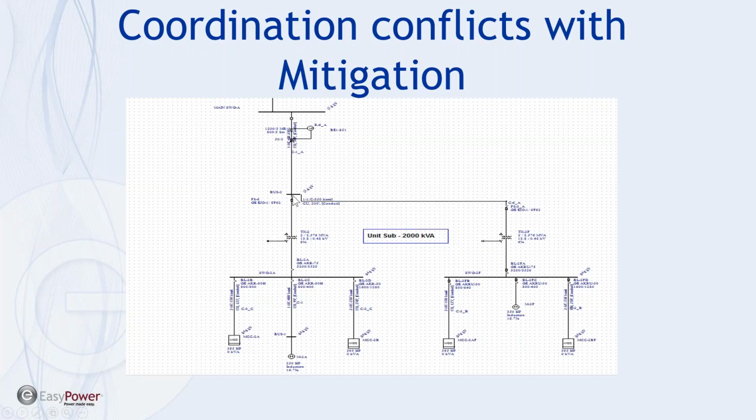And so what we've done at that point is unintentionally or otherwise raise the incident energy level above the coordinated feeder, if you will, and that may have given us headaches or heartburn when we have to go back and work on that bus hot.